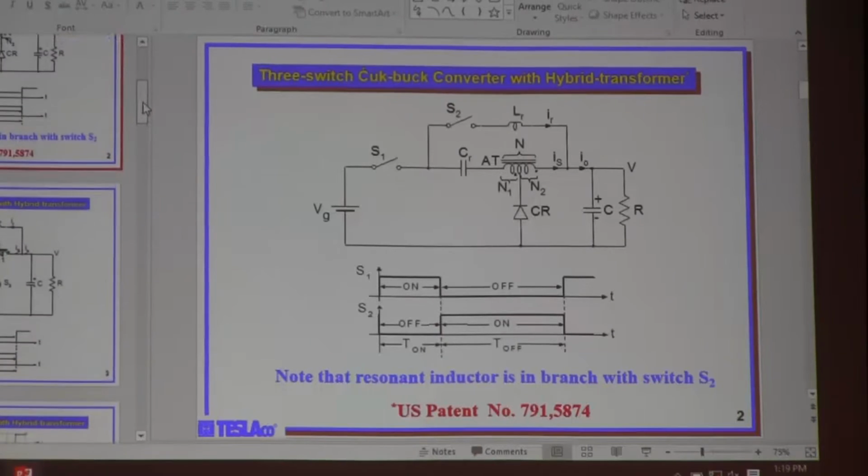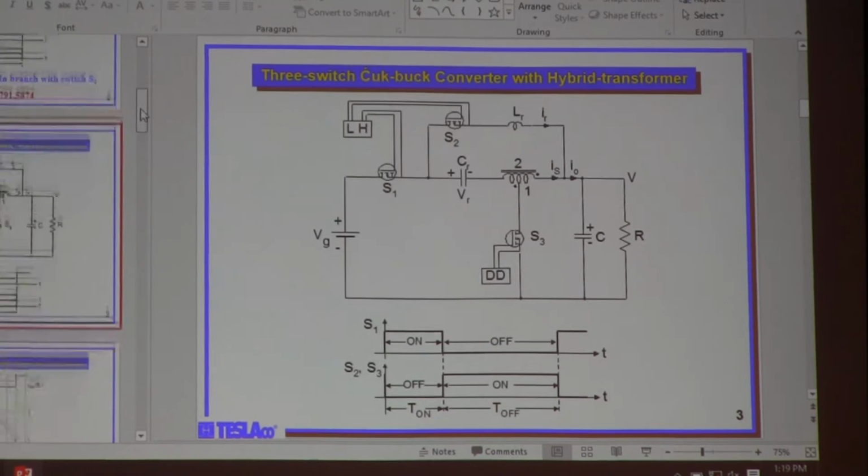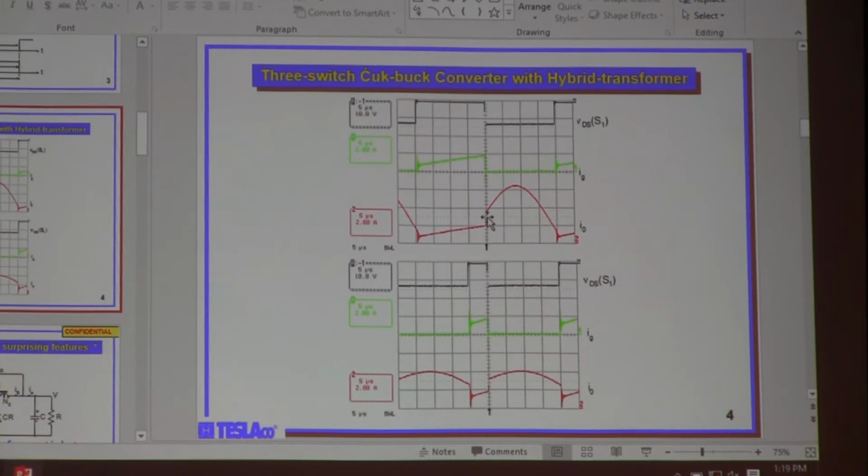Here, this version where inductance is here, or this version for that matter, it has a waveform of the switch. Watch this waveform. Still has a jump, because that inductance is not in series with the capacitance. Only series connection with the capacitance. Capacitance says I cannot change instantaneously. I'm sorry, and it starts wherever its charging finishes, or the capacitor starts a resonant current. Okay, which is what we need, right?